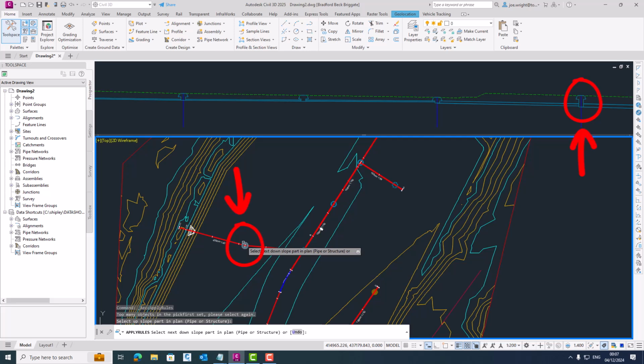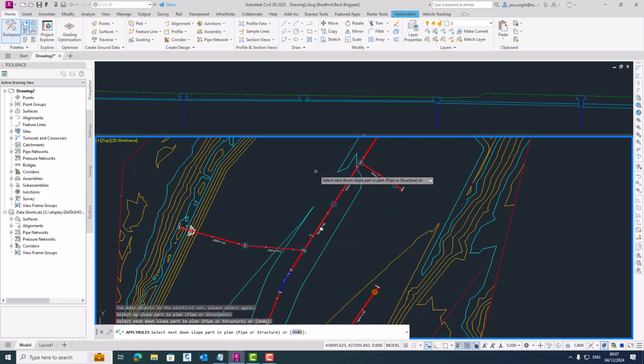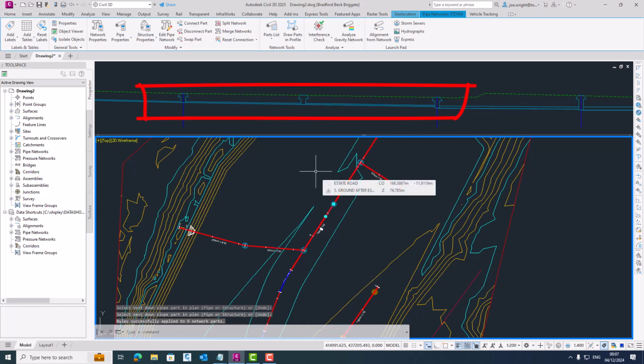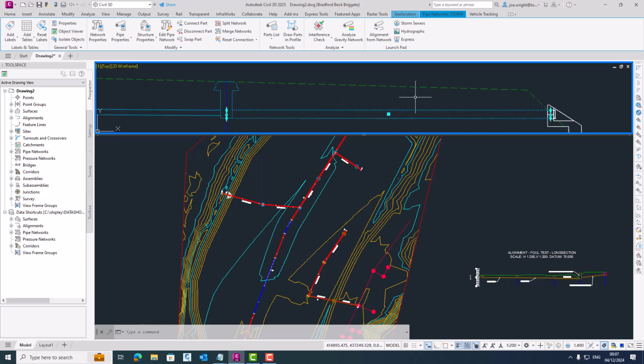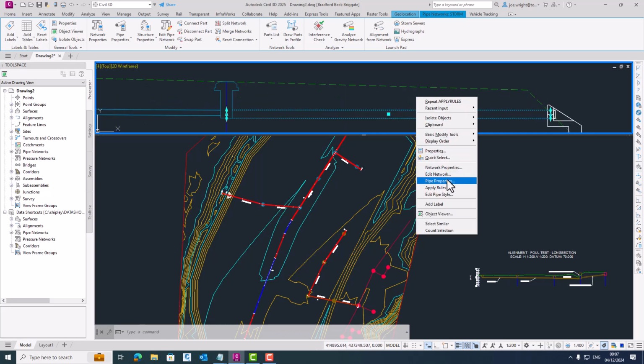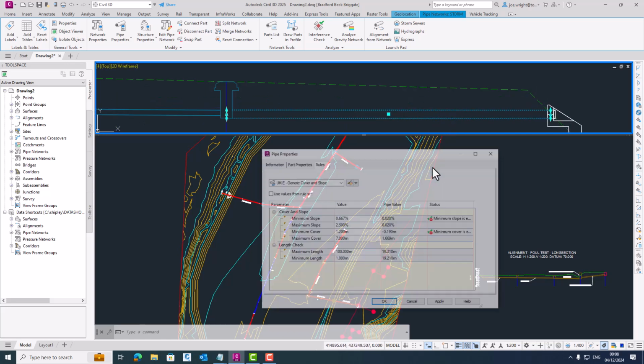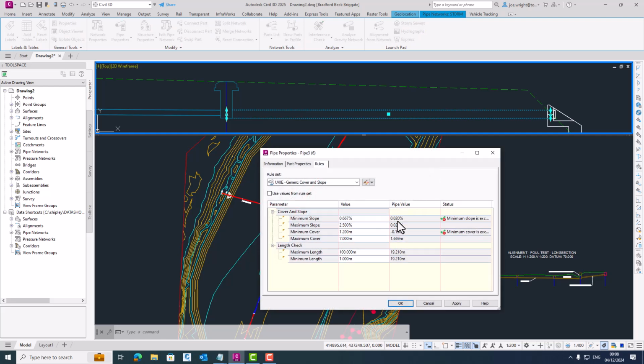After all, we spent a fair bit of time getting the outfall correct, and let's face it, the surface in that part of the drawing has remained largely unchanged. And bing! Done. Let's take a look at the final section though, the one that we didn't apply the rules to. Well, that pipe looks pretty flat now, and on closer examination we can see there's some slope, but it isn't enough.